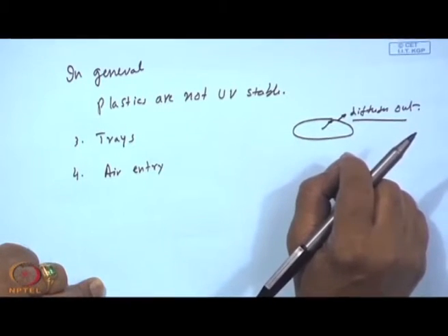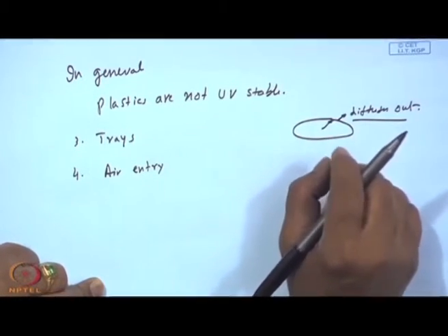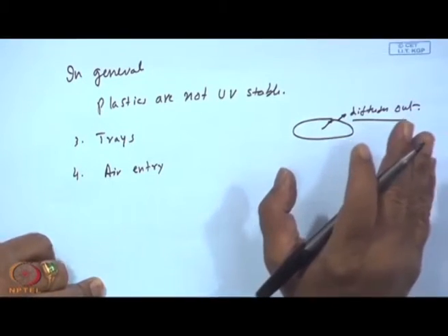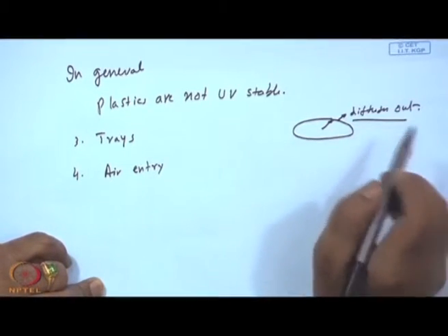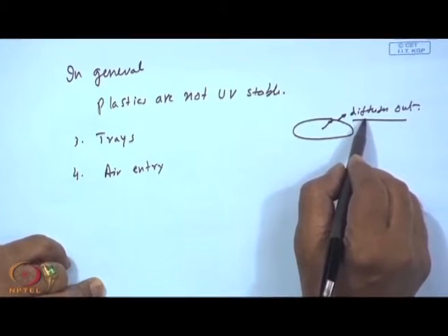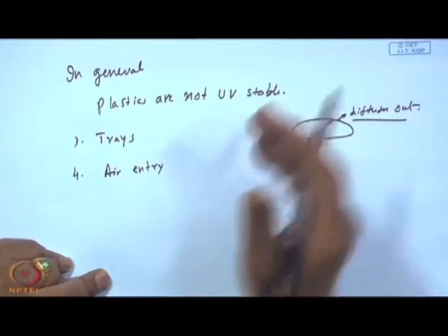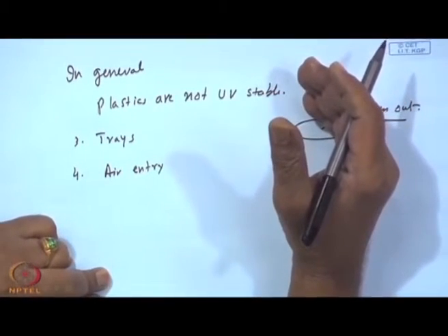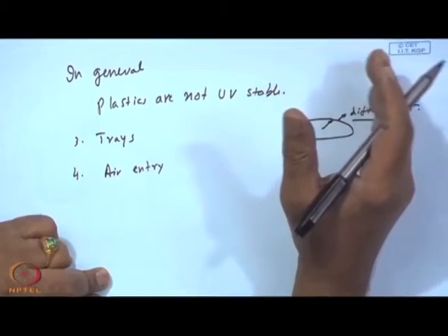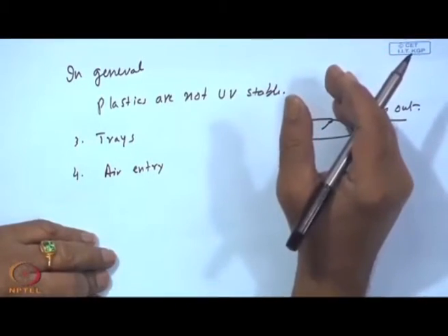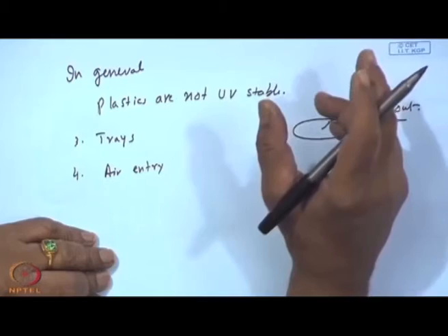And if you peel off the outer layer, it will be even easier, because the outermost layer will have less porosity and it will not allow the moisture to diffuse out. Okay, these are the tricks. As a matter of fact, if you take potato, if you peel it and cut it, it will be easier to dry. If you do not peel it, then that skin will be quite resistant to moisture diffusion. Possibly it will cook inside rather than dry.